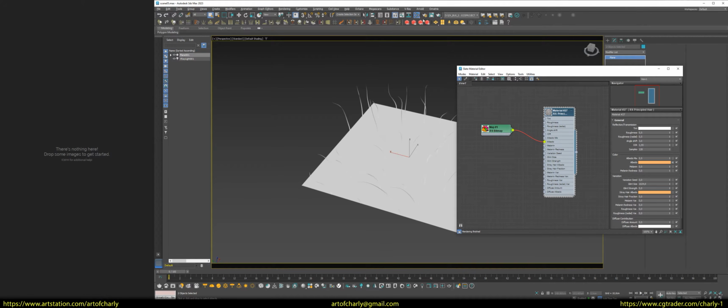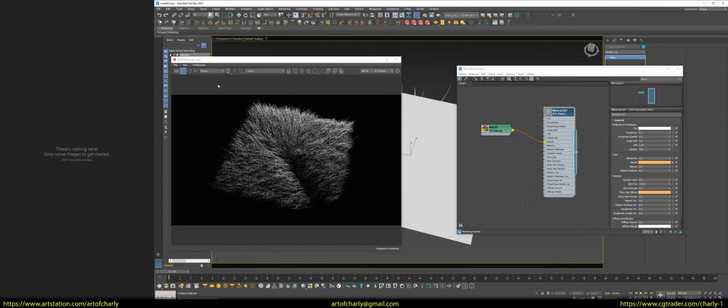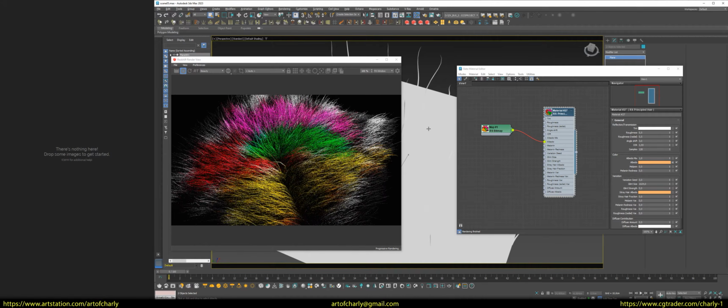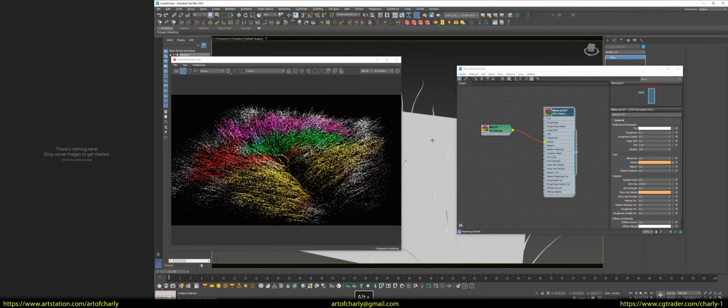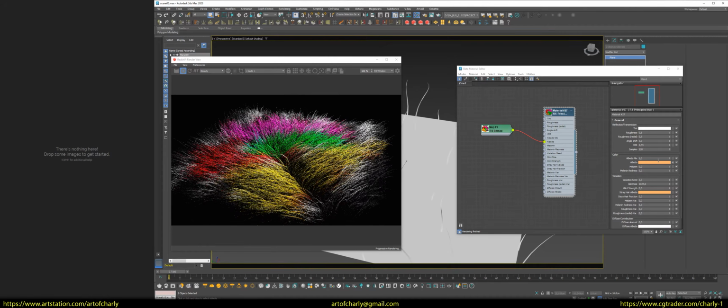And check out what you get on the renderer. We see that the color did not appear. I forgot that albedo mix works differently in Redshift than it does in V-Ray. To make the color appear, you need to set the albedo mix value to 1. Now, you need to drag the same map to the tint slot in instance mode.